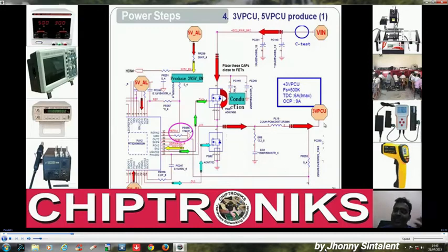It is generating lesser voltages from V in, and V in is approximately 19 volt, and we are trying to generate 3.3 and 5 volt from 19 volt through switching of these MOSFETs. Switching of these MOSFETs is controlled by the gate signals U gate 2 and L gate 2, which control the switching on and off of the MOSFETs.